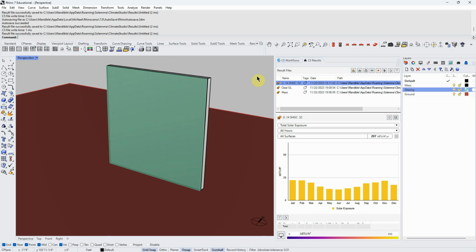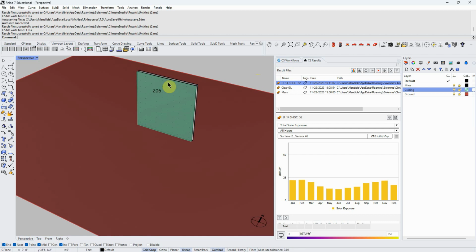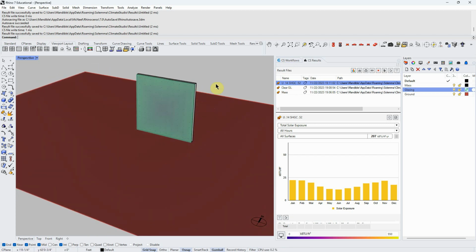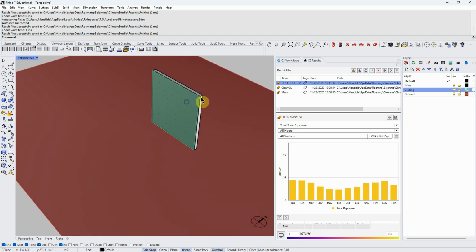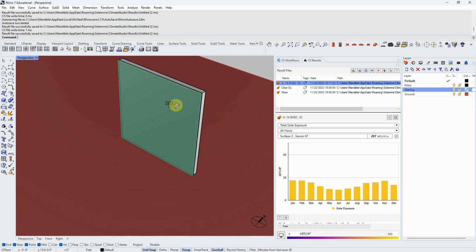One way to do that would be, when your project is in a state where you can do a thermal analysis, to make a thermal zone for the Trombe area and have the exterior facade be whatever glazing you've chosen here, or you could try different ones. That would make the Trombe wall part of the thermal analysis workflow.